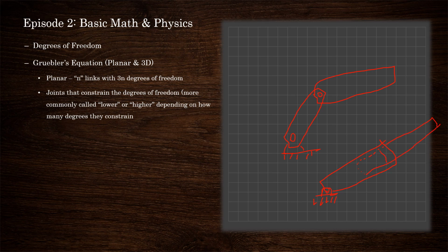And I draw a link that can move only like that. So the link is constrained such that it can move only in one direction like that, but it has lost all other degrees of freedom. So it has only one way in which it can move up and down, which means it has lost 2 degrees of freedom. This system also has only 2 degrees of freedom, one about that and one in that direction. So there are two types of joints in 2D space that arrest 2 degrees of freedom.